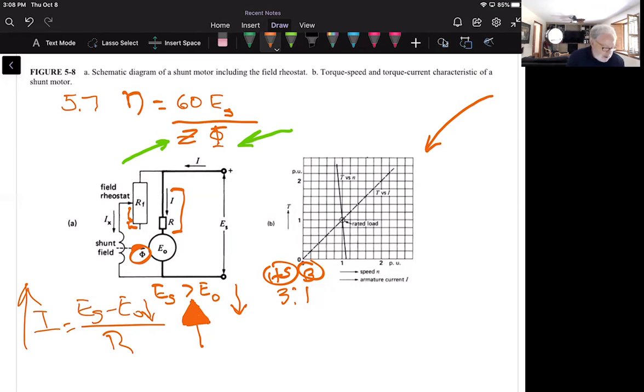That flux becomes so small that the motor has to rotate at these dangerously high speeds to induce the required counter electromotive force. Those conditions, where this drops to very low levels, we call a runaway condition. That's something we have to avoid with a DC motor, and we'll put things in place in our control system to make sure that doesn't happen.